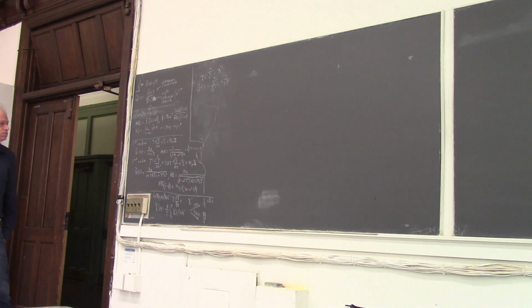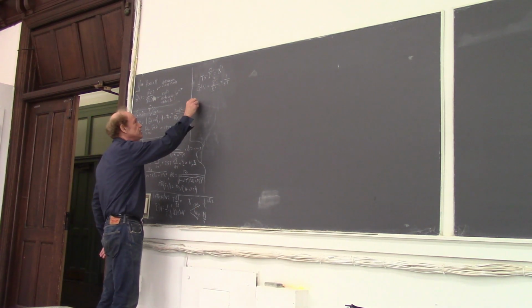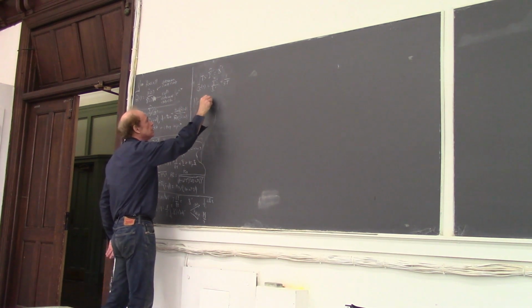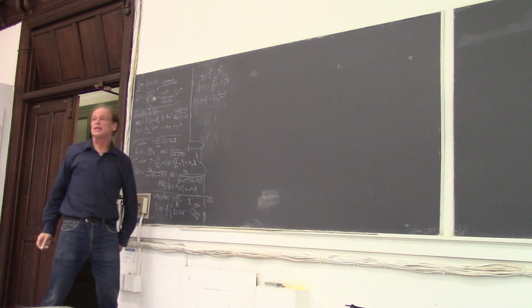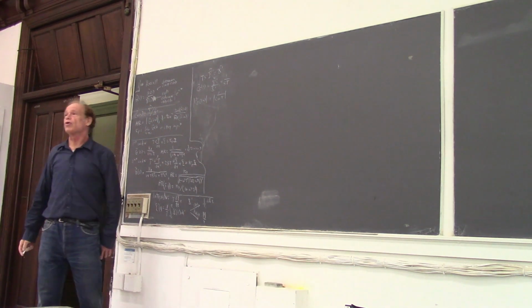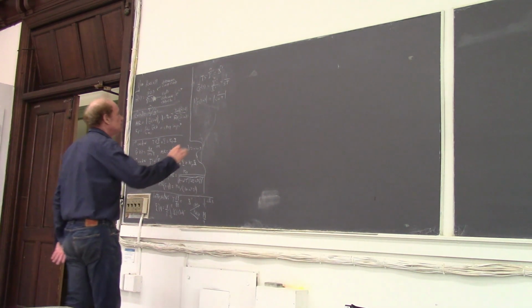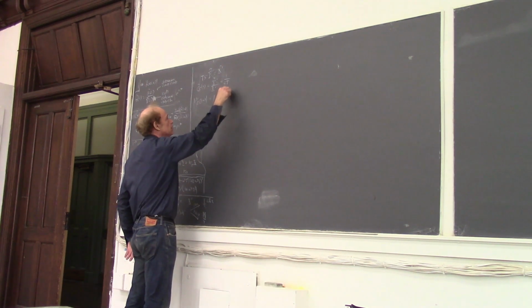Okay, so let's look at the amplitude ratio, g tilde of i omega. That's the magnitude of 1 over i omega t. Well, let's see what that is. Remember, in order to get a magnitude, I need the i in the numerator, not denominator. So the way to get i in the numerator is to multiply and divide by i.